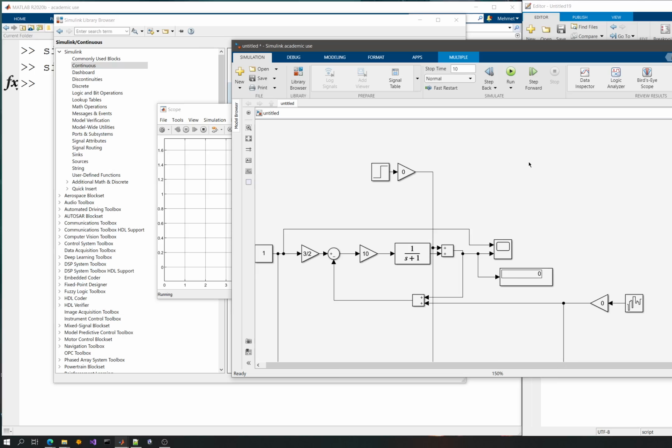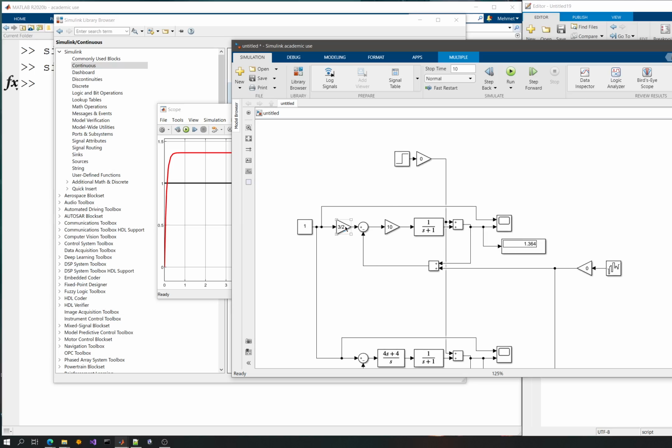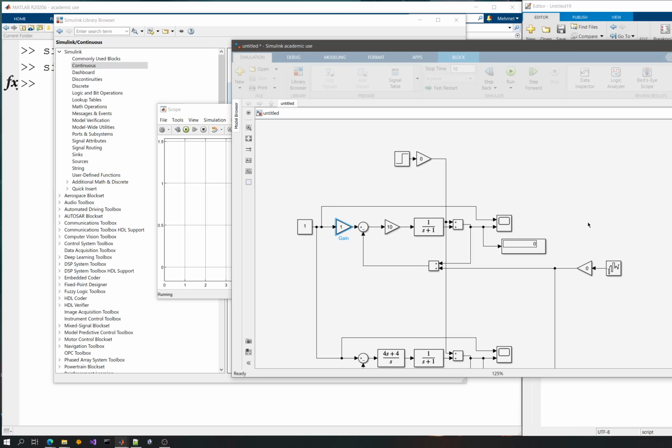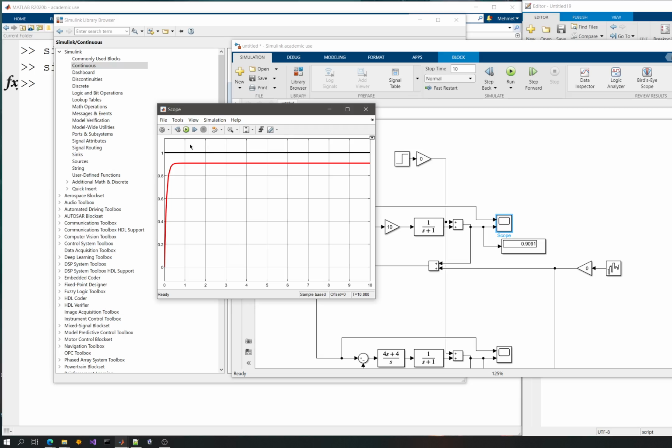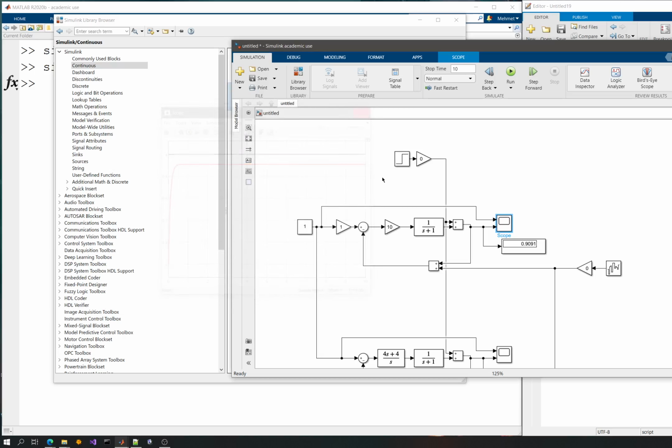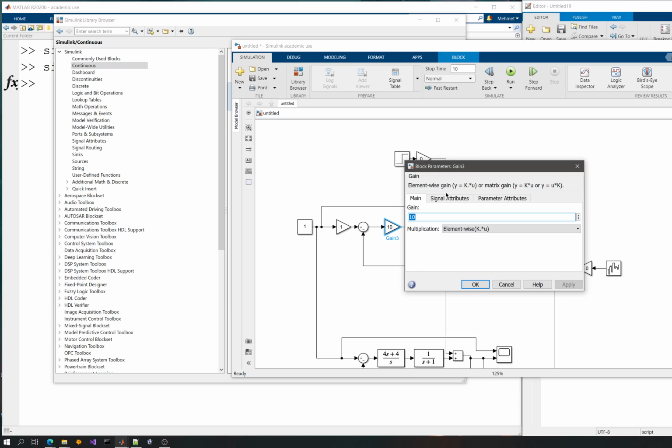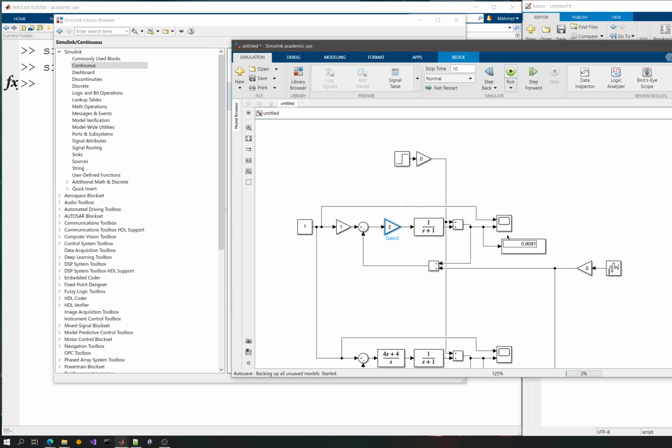Now if I want to disable both effects of noise and disturbance, I can see now that I need to change this basically. If this is 10, it should give me a 10 divided by s plus 1. Let's also get rid of this here. Let's say this is 1. Because it will not need that much of a pre-filter here, and you can see it is 0.9, but if I have a lesser gain value, let's say 2, it will not be 0.9, it will be a lesser value here.